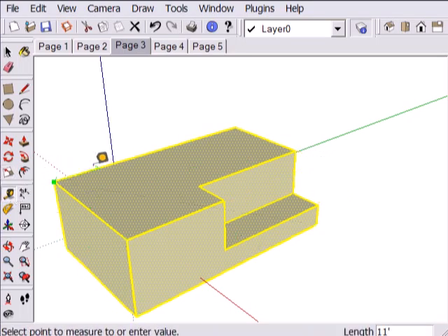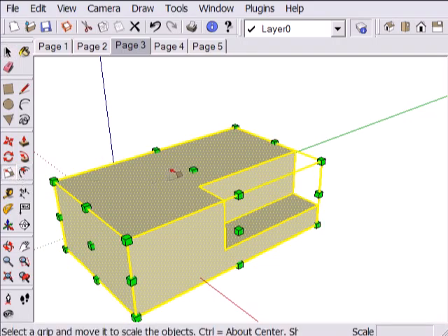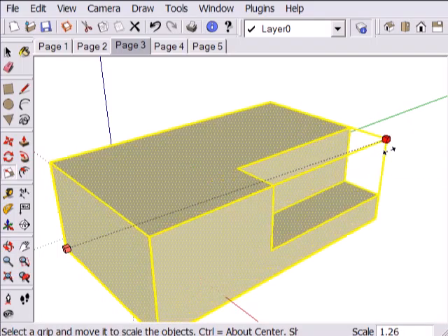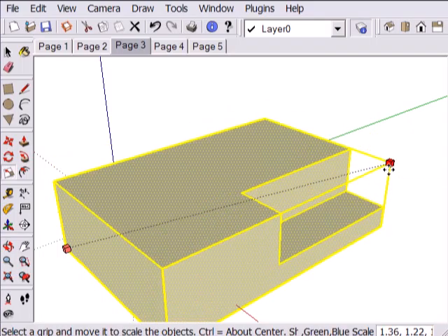I can verify the distance with the tape measure tool and read the distance down in the lower right corner of the screen in the value control box. Notice I must type the distance punctuation using apostrophe for the foot sign, otherwise the value is read as a scale multiple factor. If I want inches, I must type the inches sign.